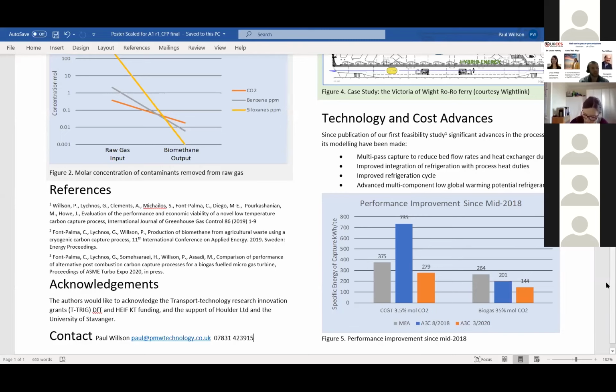We had a very similar question in the chat about the sulfur emissions. So what are you doing with the remaining SOx that have been separated? Right, the SOx comes out as part of the condensate, and that's neutralized and discharged to sea as part of effectively the scrubbing of the incoming gases. That's part of the total cleanup process. So we end up with, I guess, sodium sulfate going to sea.